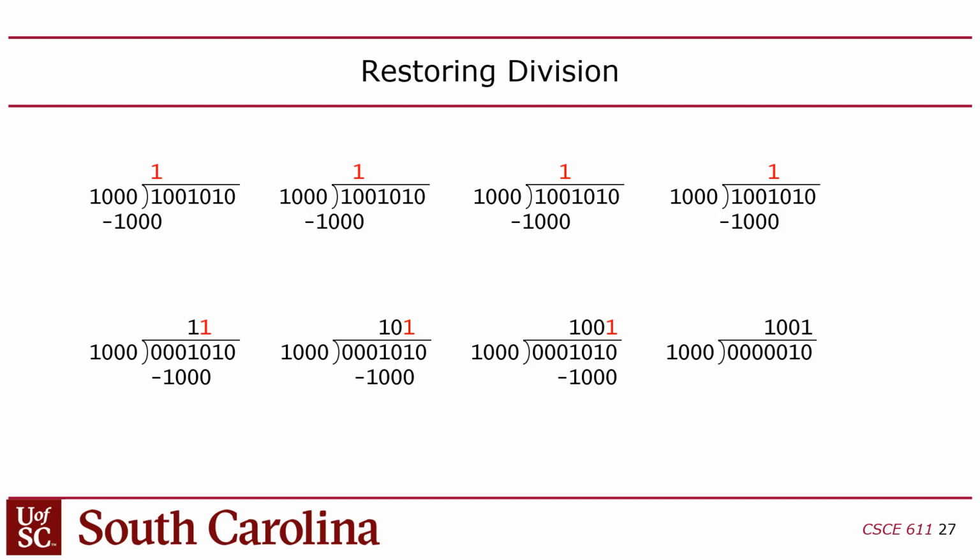So once that happened, then I keep the difference. It's 1, right? Should be 1. Yeah, it should be 1. I think I might have screwed that up. Yeah, I should have kept that one as 1. Sorry. Yeah, so basically when you subtract and you're successful, you want to keep that difference in place of the original dividend. It becomes your remainder register, right? That's the idea.